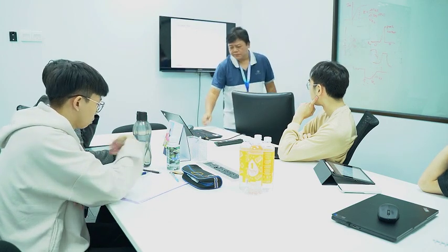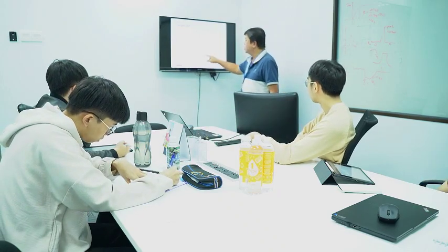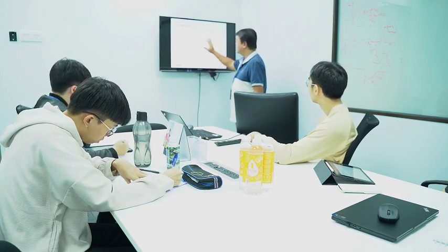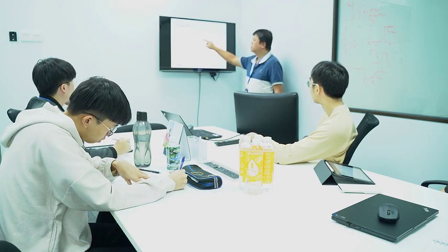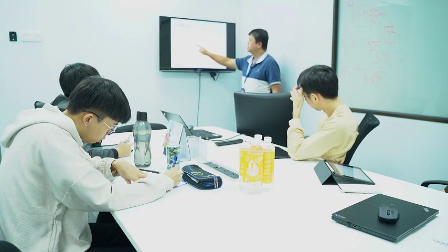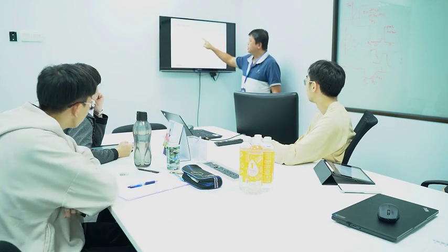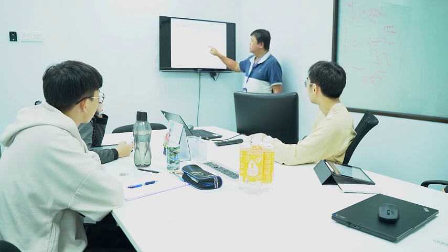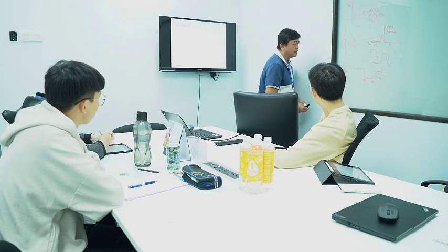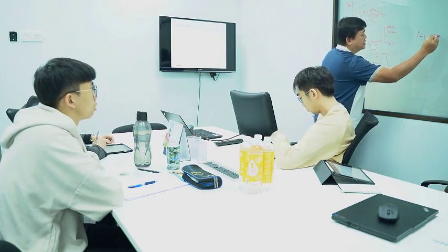Now we look at here. Look at this formula. How can we get the 1 plus SRC here? This is a voltage divider. The impedance across the capacitor is 1 over SC. The denominator is the total impedance, R plus 1 over SC. So we get 1 over 1 plus SRC. The 1 plus is a normal term we use: 1 plus SRC. Easy to remember, right?